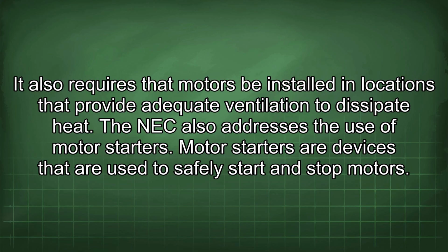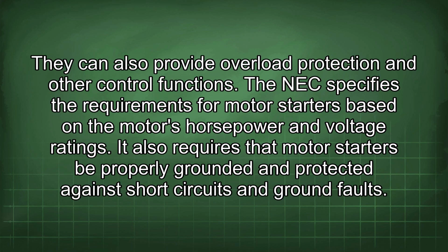The NEC also addresses the use of motor starters. Motor starters are devices that are used to safely start and stop motors. They can also provide overload protection and other control functions. The NEC specifies the requirements for motor starters based on the motor's horsepower and voltage ratings. It also requires that motor starters be properly grounded and protected against short circuits and ground faults.